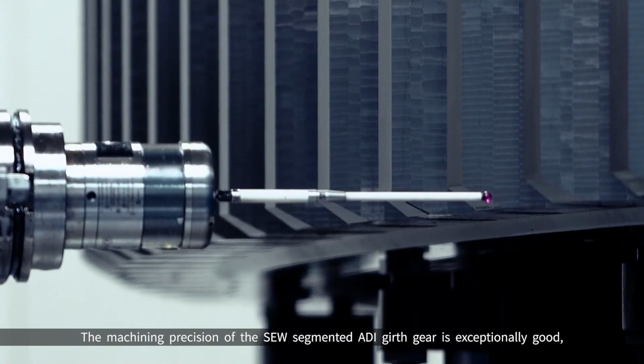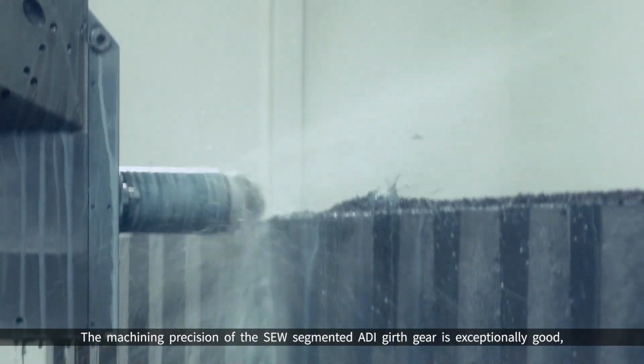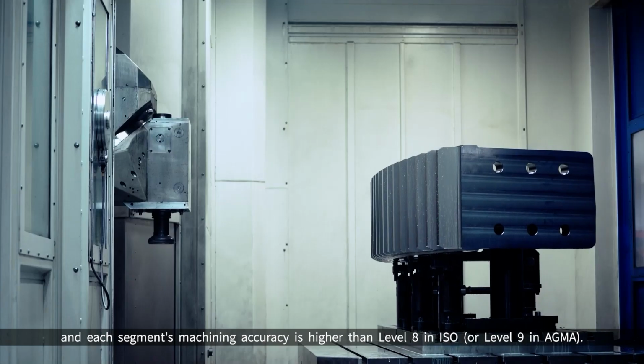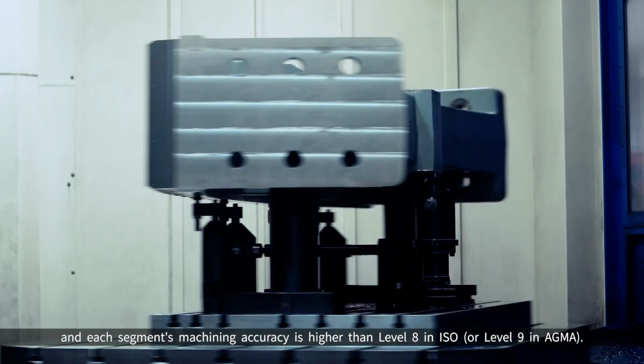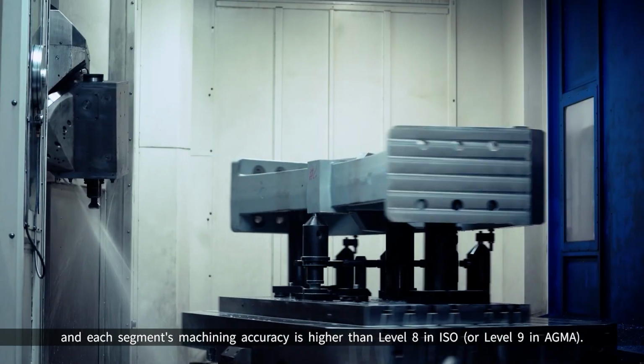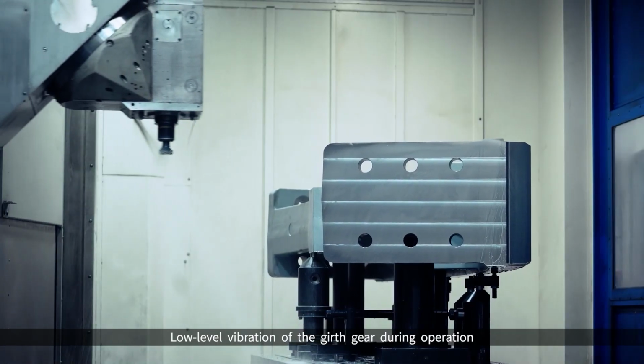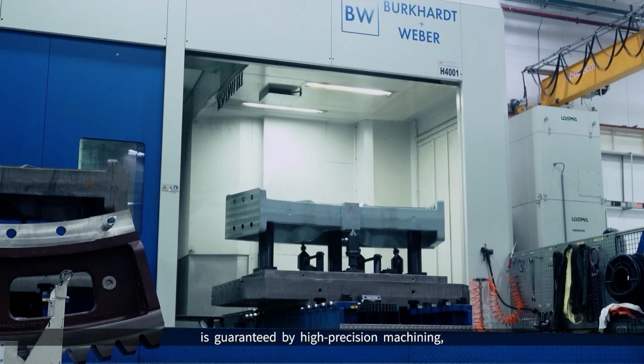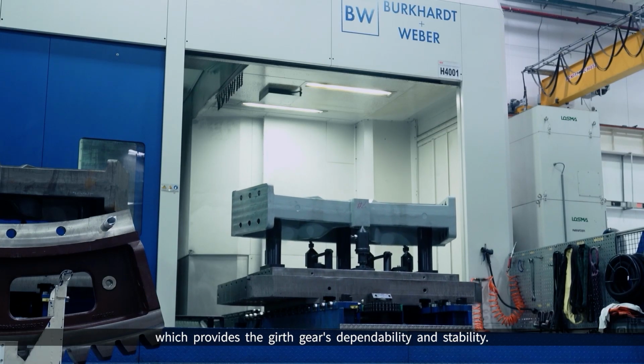The machining precision of the SEW segmented ADI girth gear is exceptionally good, and each segment's machining accuracy is higher than level 8 in ISO or level 9 in AGMA. Low-level vibration of the girth gear during operation is guaranteed by high-precision machining, which provides the girth gear's dependability and stability.